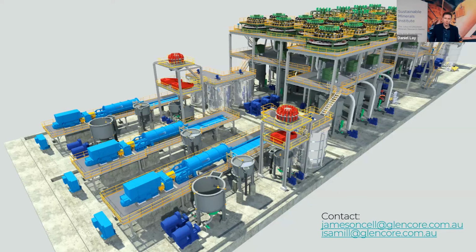For a long time, that's where the Jameson cell was marketed. There are multiple examples of cleaner scalpers being retrofitted to existing plants or put into new plants, which then expanded to re-cleaners, and eventually to full cleaner circuits. A good example of that is the Mount Isa circuit, where we have 3 cells that replace the entire copper cleaner circuit. Then ultimately people started asking, why can't we do this as a rougher? That's really been the focus over the last couple of years.